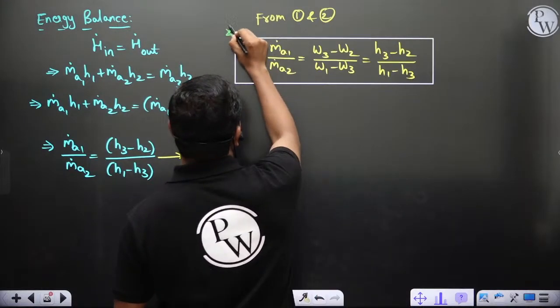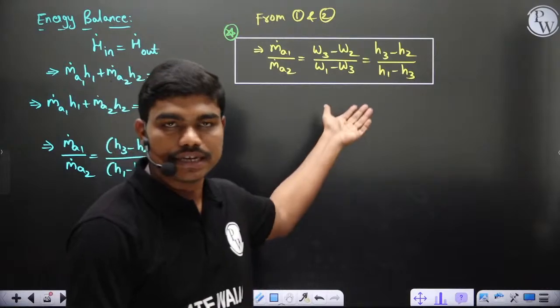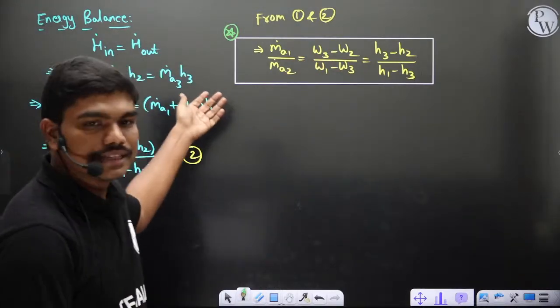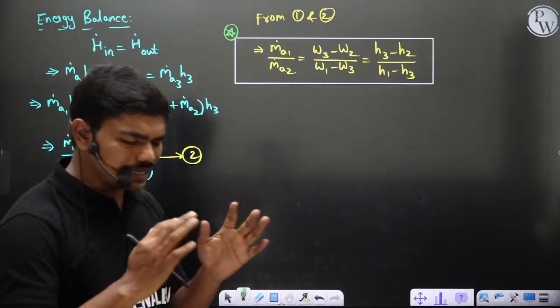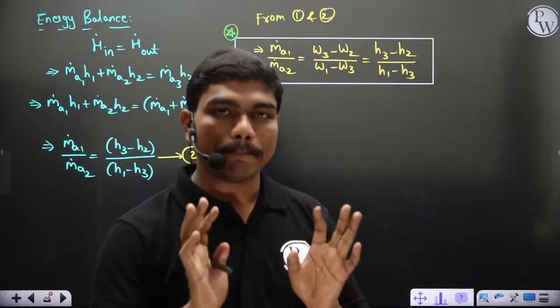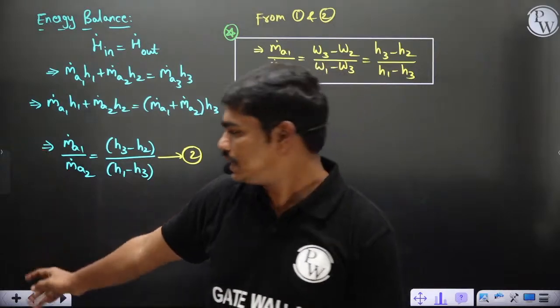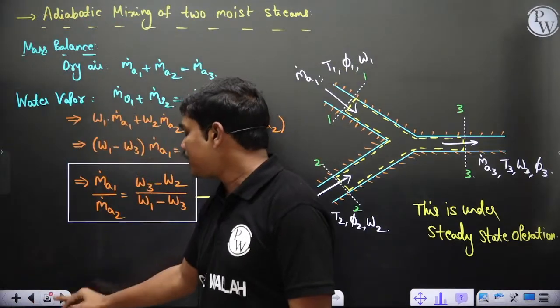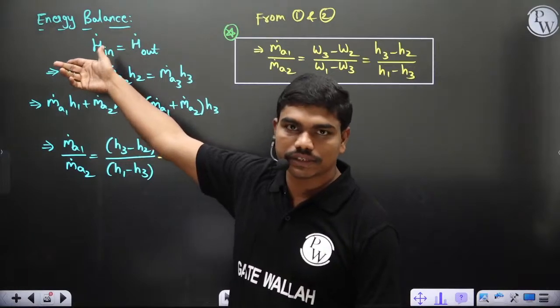So this is what you have actually here in this case, and this formula some of you might have already seen in case of adiabatic mixing, okay. How many of you have seen this formula in case of adiabatic mixing? If you take any thermodynamics or applied thermodynamics textbooks, you will normally see adiabatic mixing. But whatever the process they give you, simple basic thermodynamics has to be known. If you know simple basic thermodynamics, apply continuity, and apply energy balance, you will get the equation. And this is basically from your steady flow energy equation, okay.